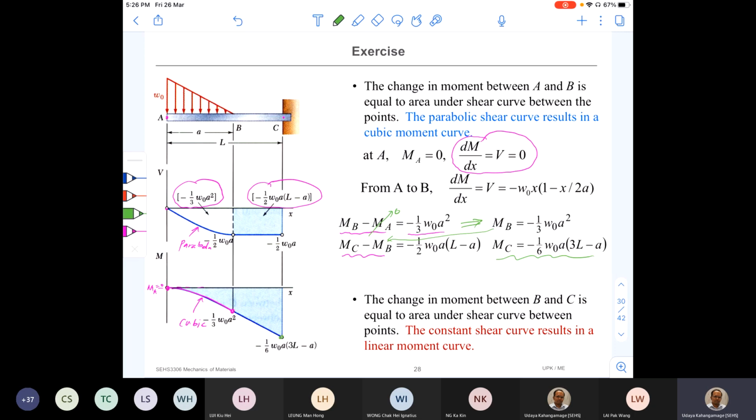Therefore, like in here, right? Not here. And by looking at the shear force diagram, where the variation is constant, no variation, the bending moment variation should be linear. So we mark the two points and connect them with a straight line. So it is linear.